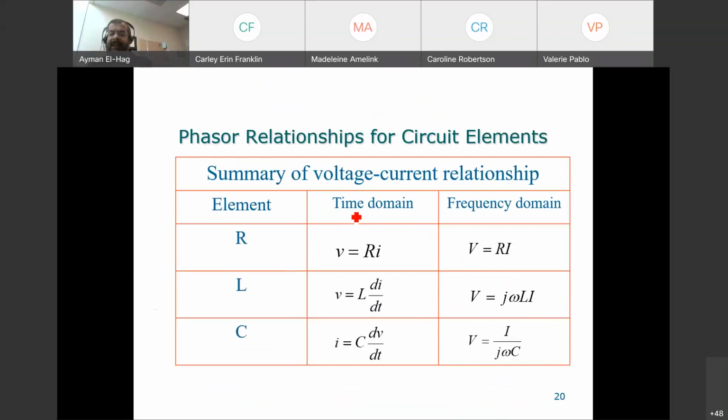So this is, in conclusion, what exactly we have, or our knowledge about R, L, and C in time domain and in frequency domain. Frequency domain, which we call the phasors, same thing. So we call it sometimes frequency domain, and sometimes we call them phasors. So in time domain, Ohm's law, this is the relation between V and I. V equal to Ri. In frequency domain is exactly the same. There's no difference. So the resistance stays the same, either you talk about time domain or frequency domain.